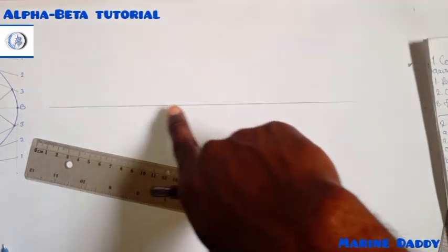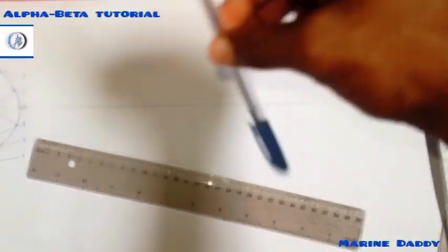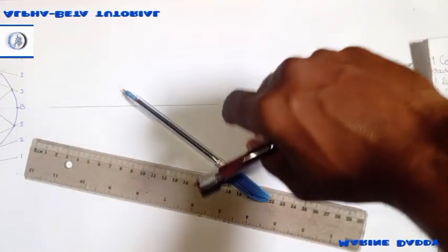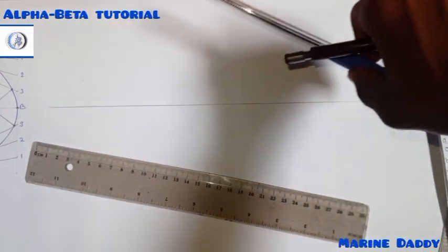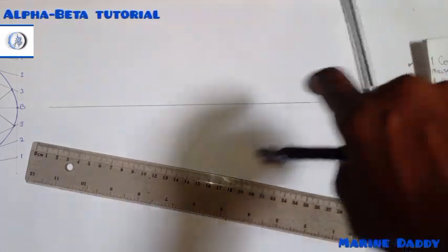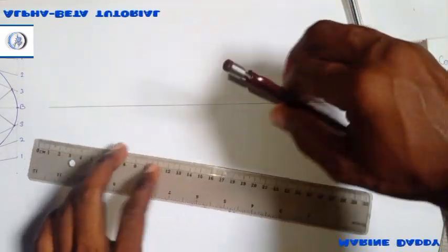Please, this line is not a fence in real life. I'm making it thick because I have a pen, a biro that will make it thicker when I'm trying to outline. So please, for your own case, make sure your line is very faint and don't clean construction lines. Very very important.